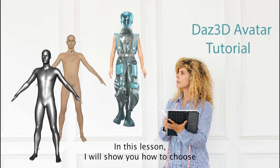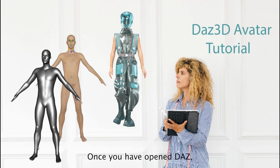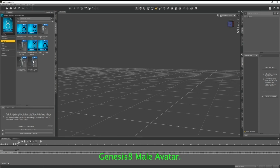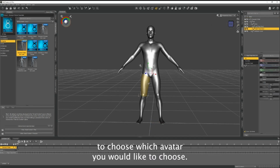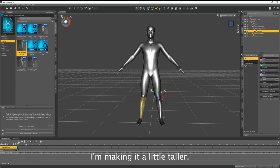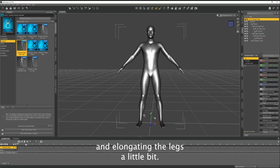In this lesson, I will show you how to choose and create your own personalized avatar in DAZ 3D. Once you have opened DAZ, go to Product, Figures, Genesis 8, Male Avatar. But this is up to you, which avatar you would like to choose. I'm going to make a few changes. I'm scaling the avatar, making it a little taller. I'm selecting left shin and right shin and elongating the legs a little bit.